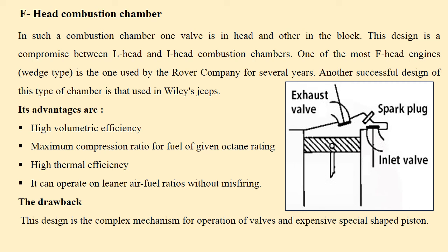The advantages are high volumetric efficiency, maximum compression ratio, and high thermal efficiency. Also it can operate even at a lean air fuel ratio without misfiring. Drawback: designing a complex mechanism for operation of valves and an expensive special shaped piston. That is a disadvantage.